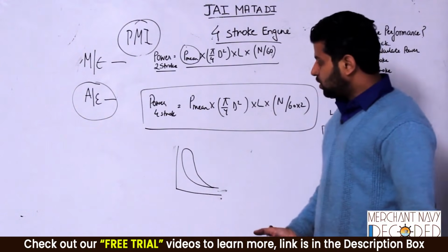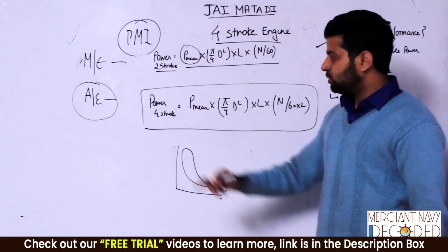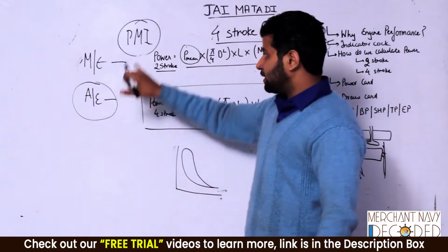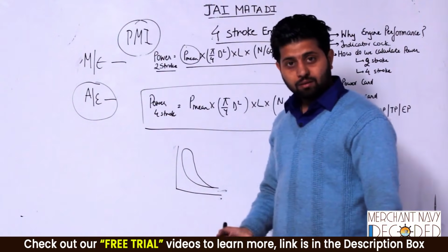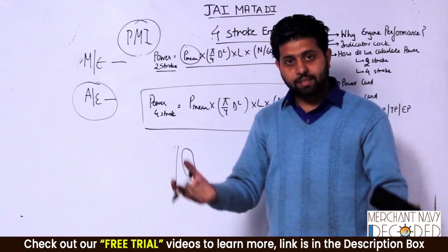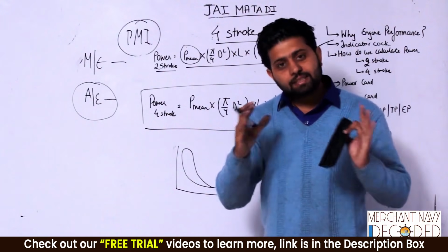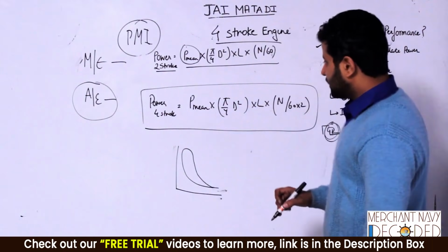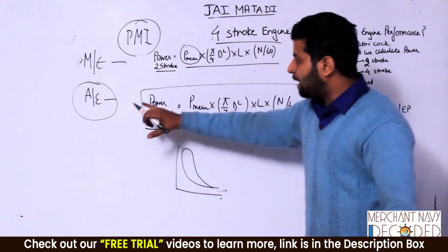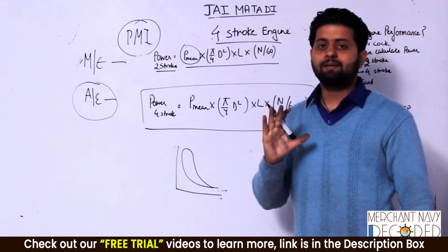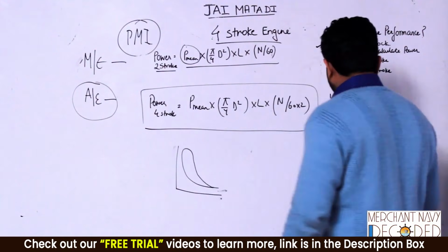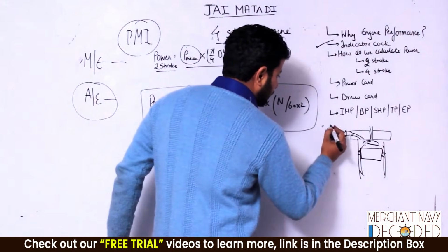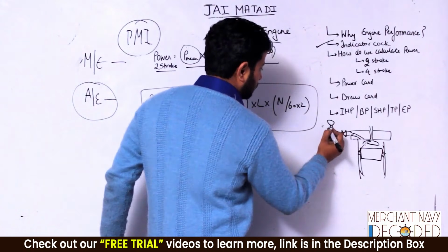So out there, what we do in auxiliary engine cases is, either the company should provide us with an electronic PMI where we can get everything exact, and in case they have not done that, then what we do is we calculate the peak pressure developed by the auxiliary engine. So we connect an instrument which has a gauge fitted over here.